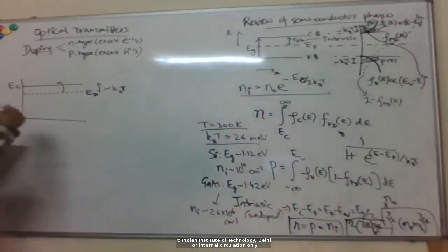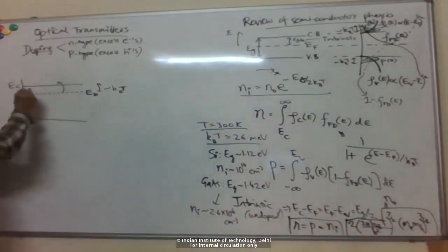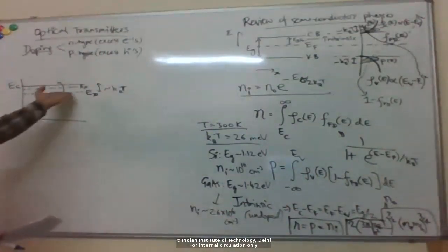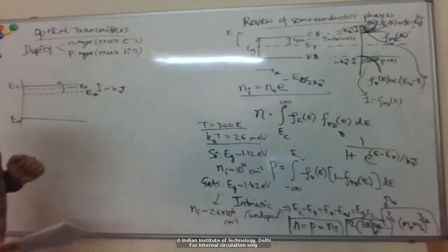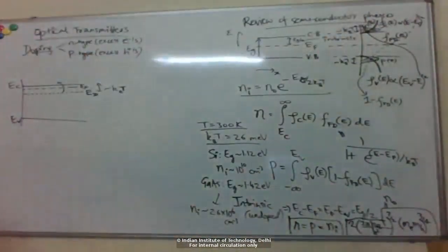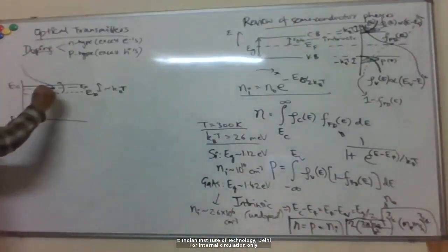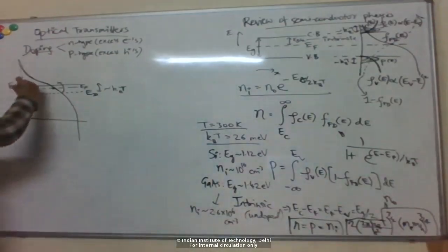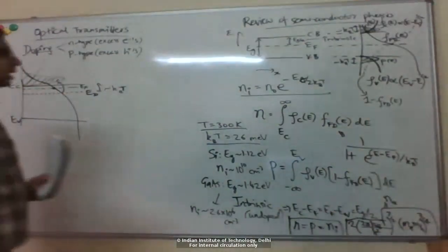Okay. So what that does is shift the Fermi level from the middle to close to the conduction band. Because of this mechanism, more electrons can occupy my conduction band. Effectively, it shifted the probability distribution upwards. Now this probability distribution extends a lot more into the conduction band, or the values are much higher here. So when we multiply by the density of states, we get a much bigger number here, so this number goes up a lot.